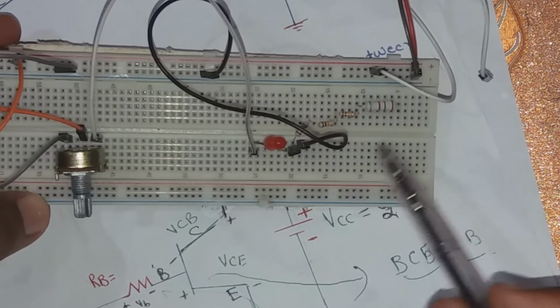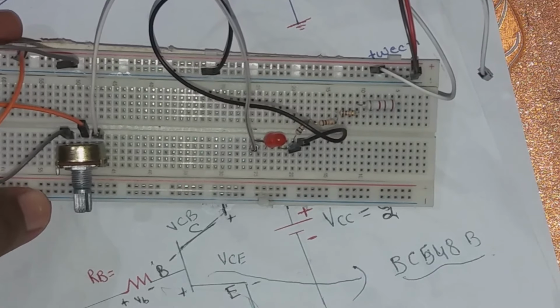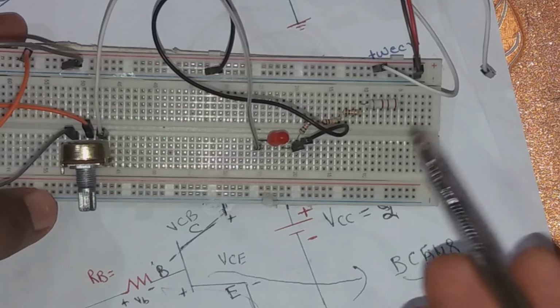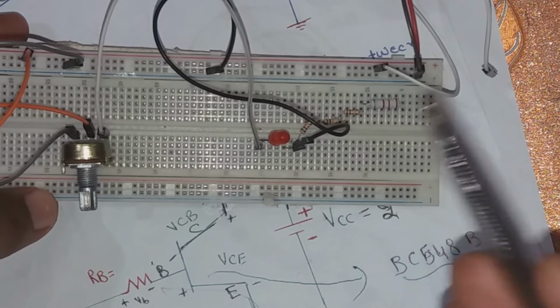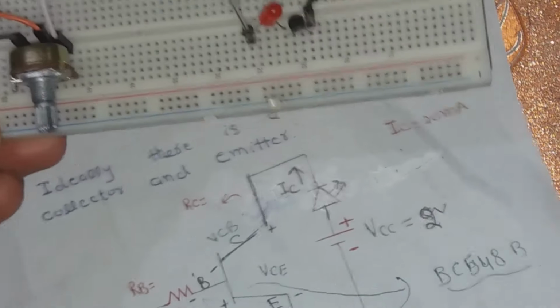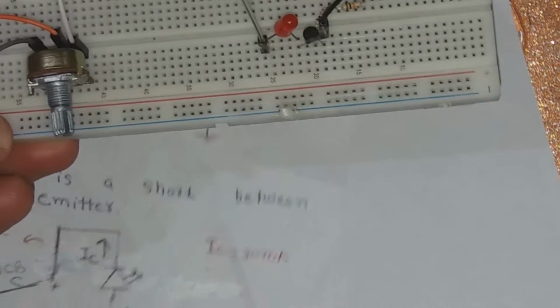But you can ask this question, why have I used 4 resistors? Well, basically 32.25 kilo ohm was not available, so that's why I connected 3 10k resistors and 1 2k resistor in series, and I get a value that's very close to 32.25 kilo ohm. So that's it.